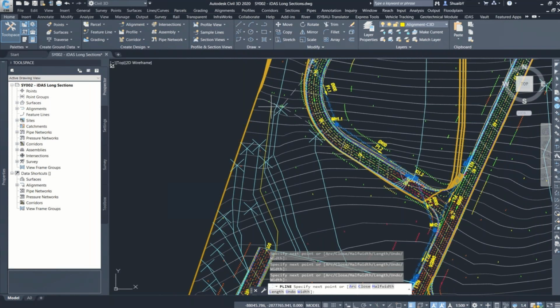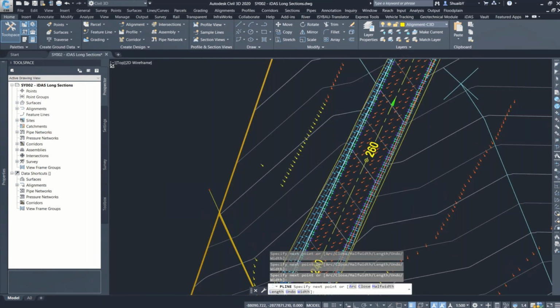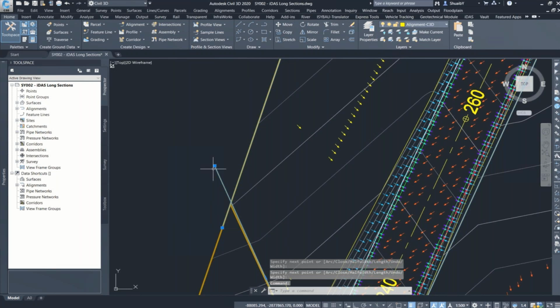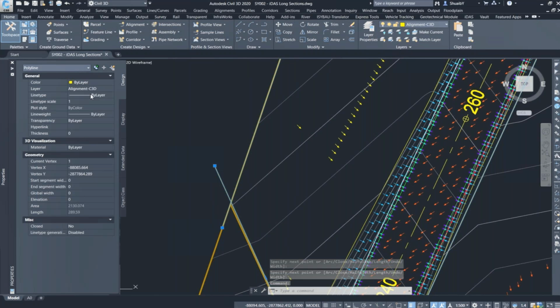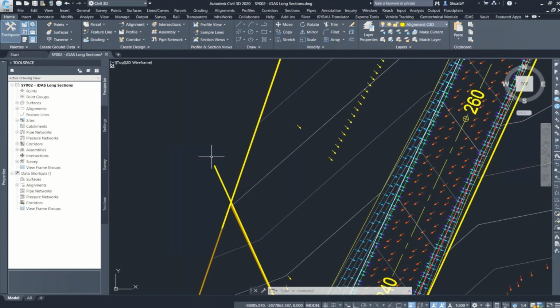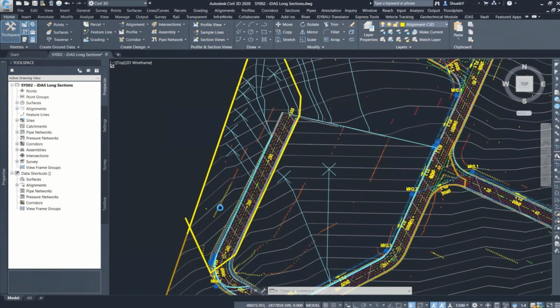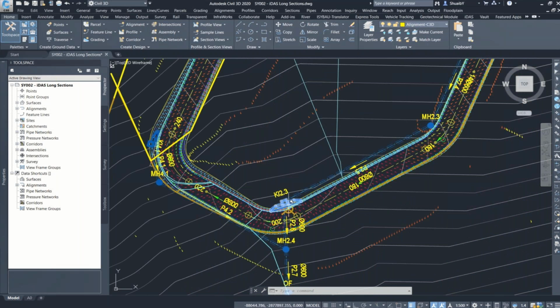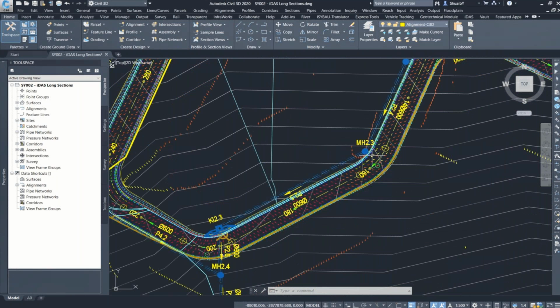Yeah, so let's just draw this very quickly. Again, I'm doing it very rough. You will be much more detailed in your approach, maybe much more accurate. But if you know about surfaces and the data, you can cater for those discrepancies. So you don't have to be 100% accurate here. So I'm just going to cross there, which is very important for generating the next steps. So I've created the catchment. I am just going to make it a bit bolder. Here we are. And this is the contributing area for that curb inlet there.